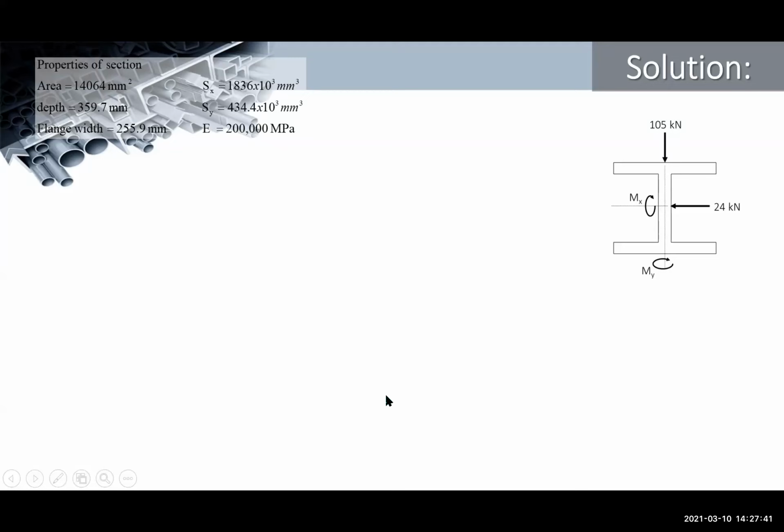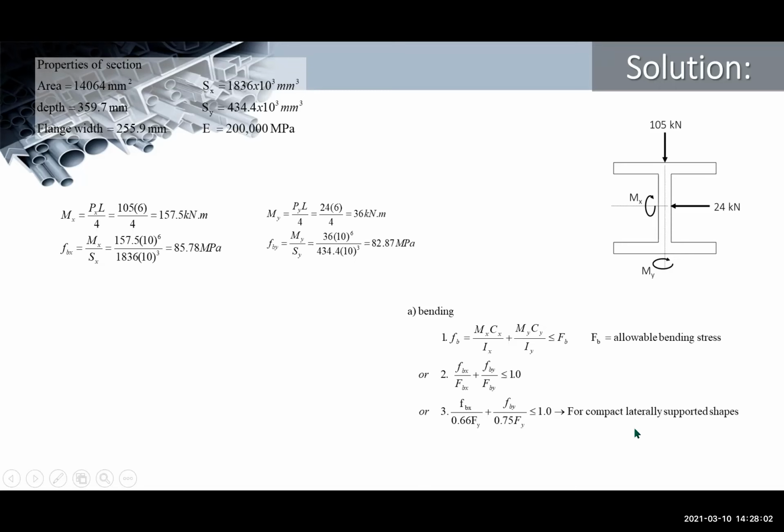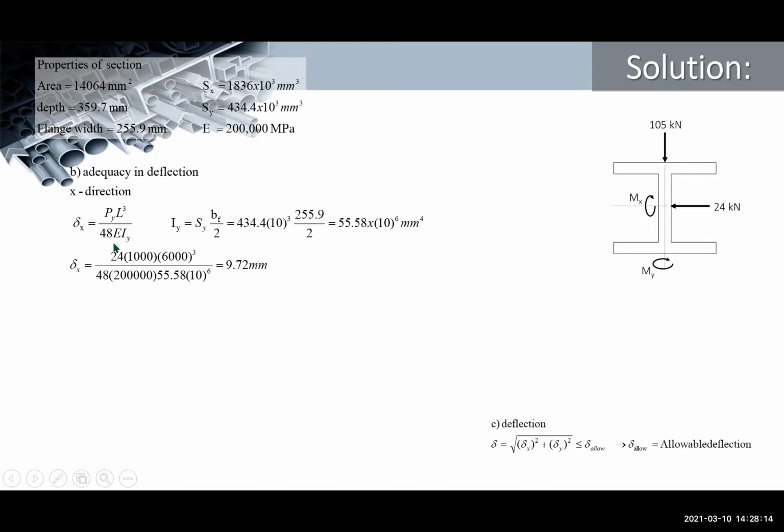If you recall the method of superposition in structural analysis, you memorized that, right? When we remove a redundant, then apply a force, then compute the deflection. Those are the typical deflection formulas. For deflection, the resultant deflection should be less than or equal to the allowable. For a simply supported beam with a load at the middle, that is PL cubed over 48 EI.